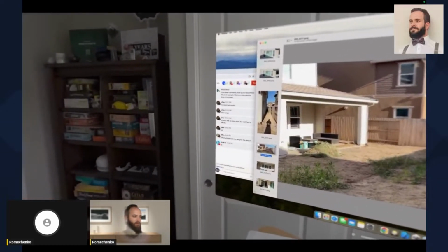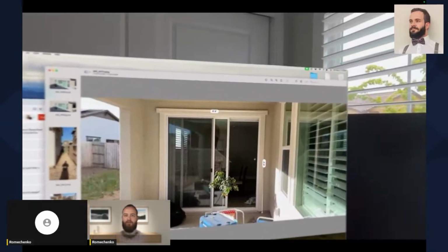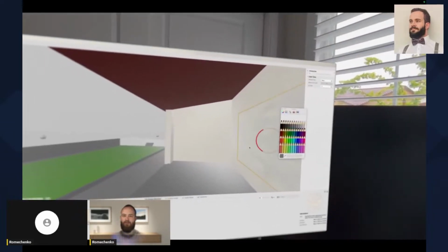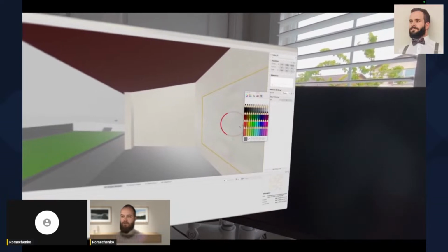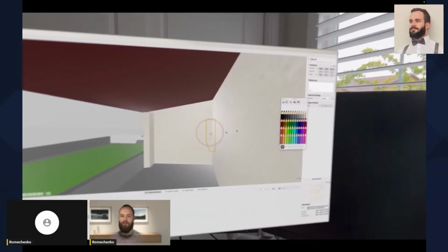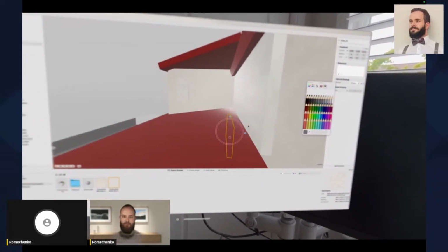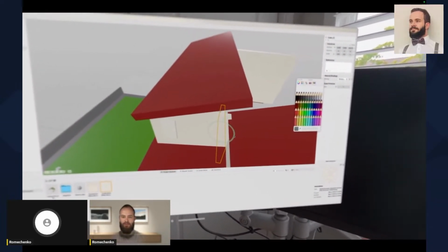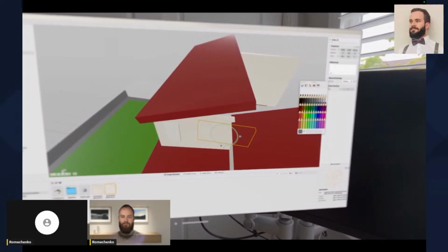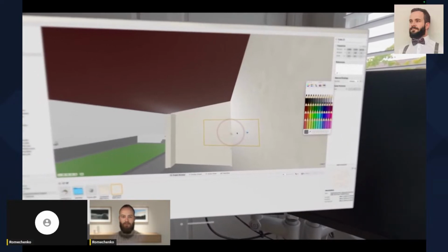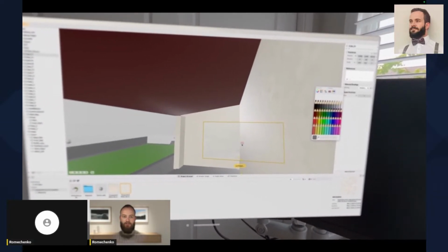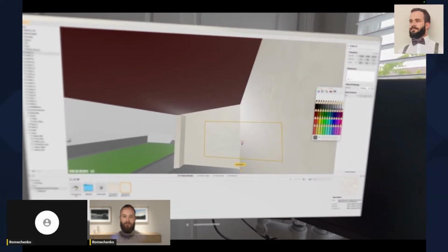And how big was that door? That door was 8.75 by 8.5. So let's move that guy over here. Get the rotation this way, 90 degrees. Bring it back up to just barely dent in. Okay.